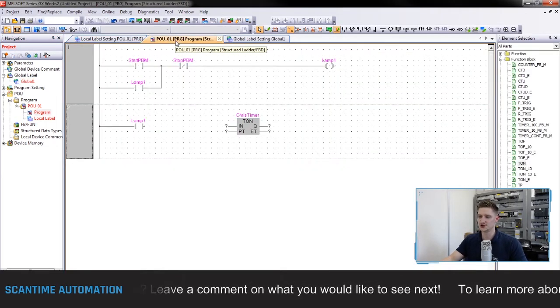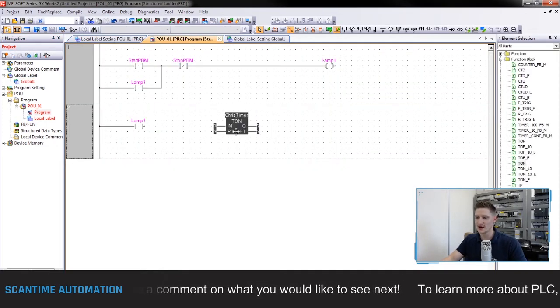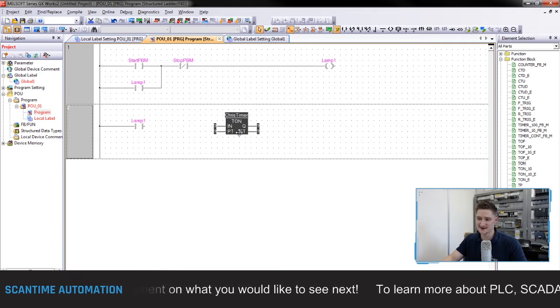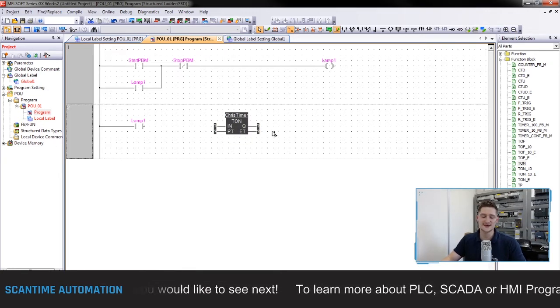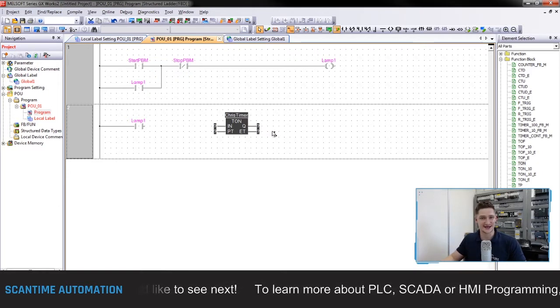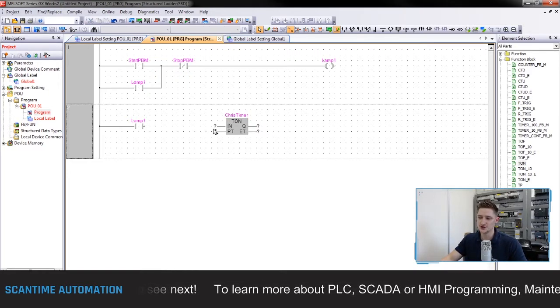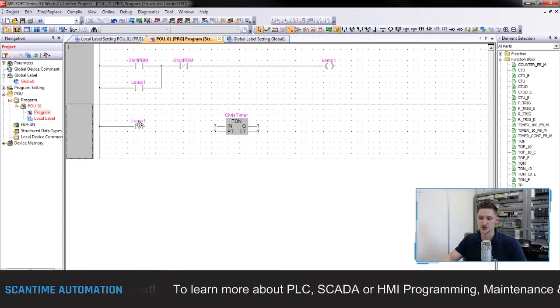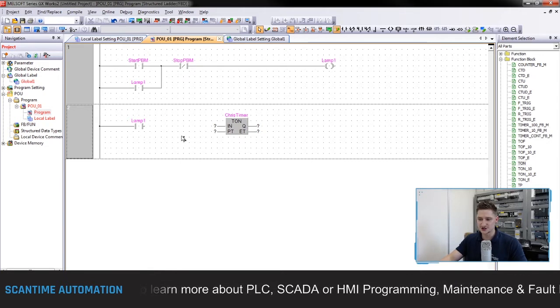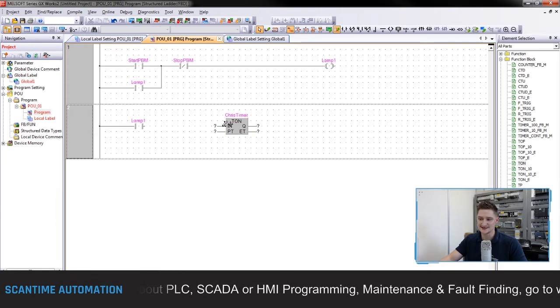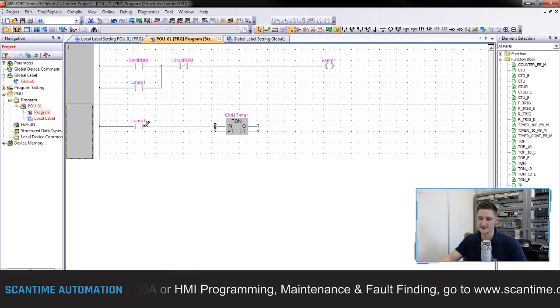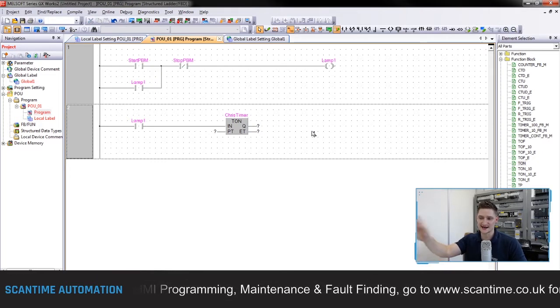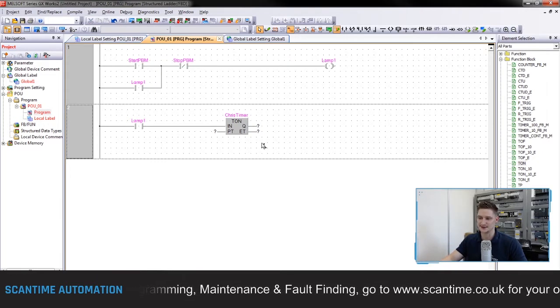Let's go back to my POU. And when you have your POU, you can see there we have our input, our PT, our Q, and our ET, just like we do inside a Siemens. Now what I want to do here is tie this input to my lamp condition. To do this, again, all we need to do is hover along this node until you see the pencil icon, click once, move to the contact, and then click again. And that there ties our lamp contact up to this timer.